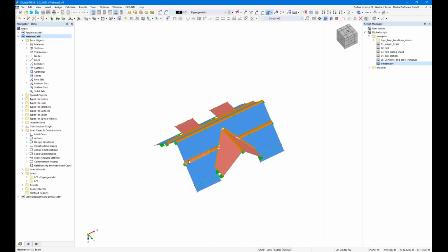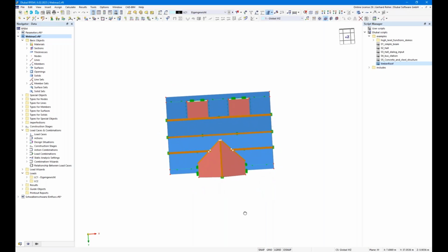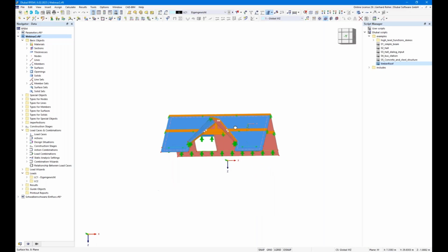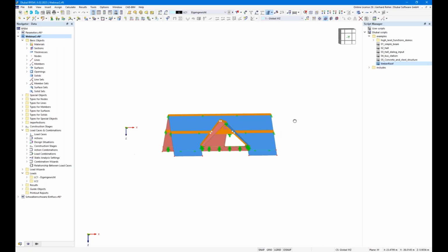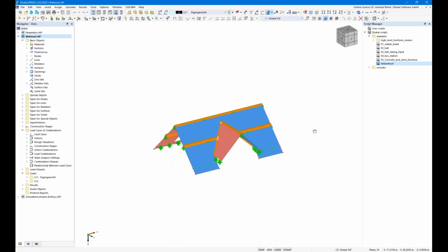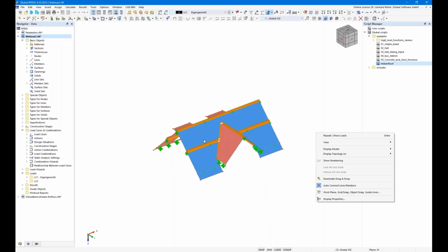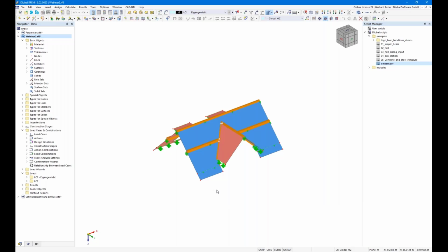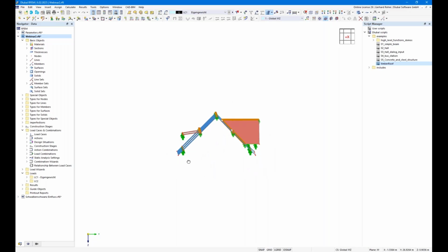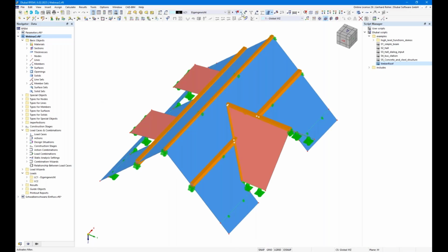Is it on the safe side to design the purlin with the whole load from this rafter, for example, or maybe when this building here is taller, then of course maybe this is design giving, because this gives you a nodal load here, or it gives you a nodal load here in the purlin in the center. So that's always hard to get a good approximation. Maybe too much load is too uneconomic, especially for the next parts. Maybe there's a column underneath and maybe another beam underneath the column and so on. Maybe the load is then too much, and it would be good to have the real distribution. Okay, so let's check the loads here.